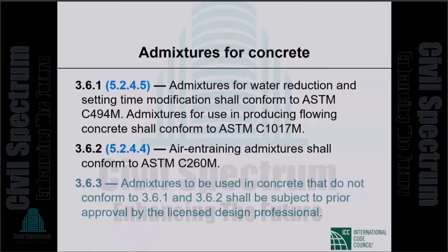Admixtures for use in producing flowing concrete, that is self-consolidating concrete, you don't have to vibrate, shall conform to ASTM C1017. That is becoming a major subject in itself these days, the self-consolidating concrete. There's a lot of development, obviously not within our scope today, but a very interesting field that has emerged. Air entraining admixtures, the spec is C260.